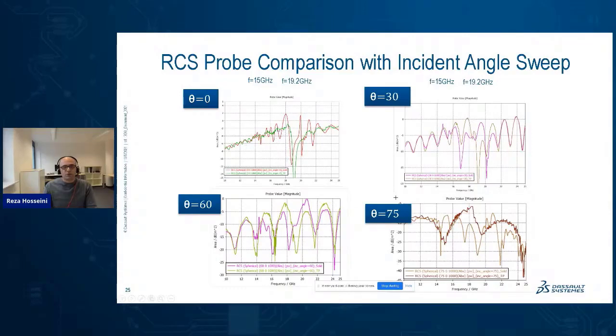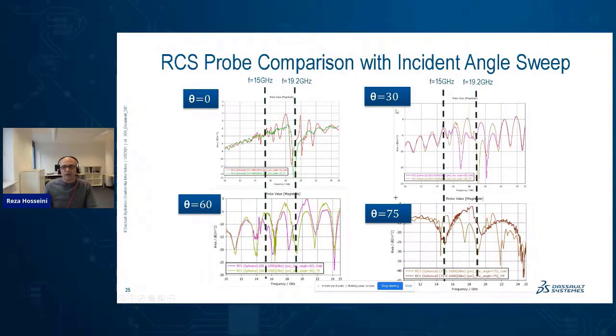But when it comes to the curved structure, we see that this red line, which is the full geometry, does not follow the SIMPanel very well. The SIMPanel remained the same, but the full geometry is not following that much anymore. So the difference starts to appear, and for different angles we can see different behavior.